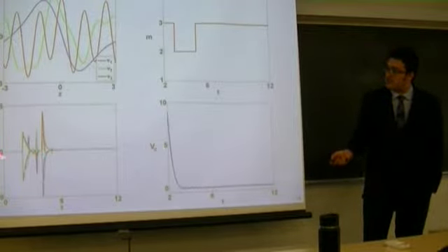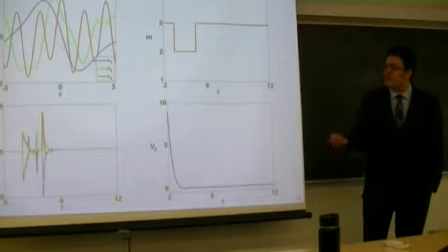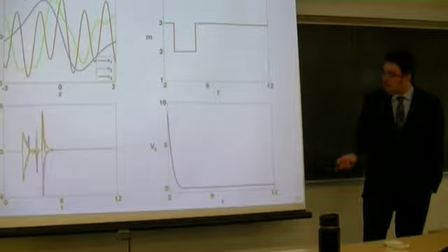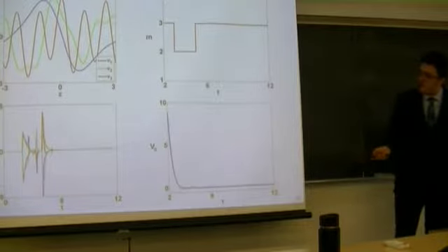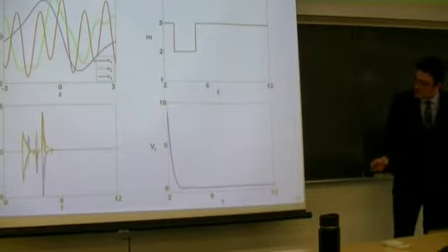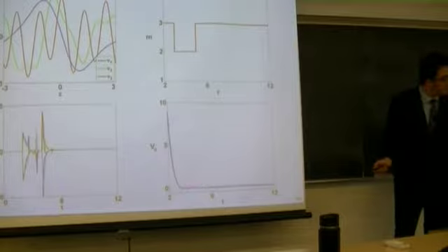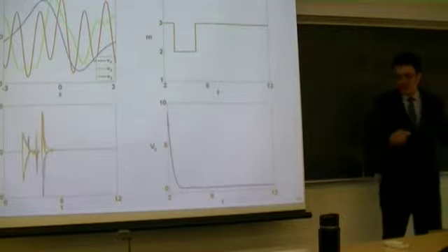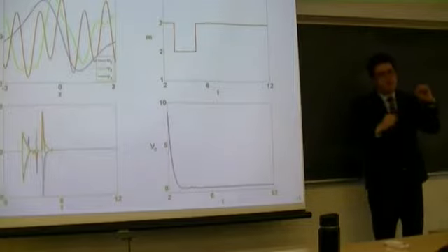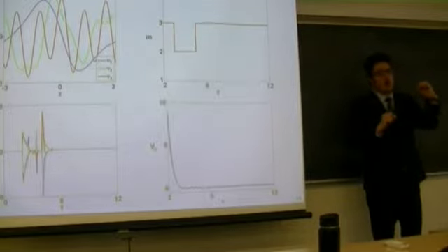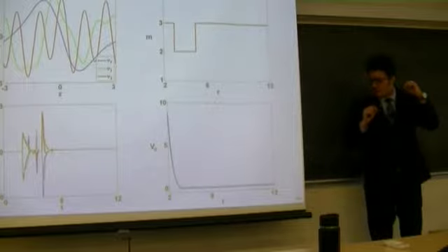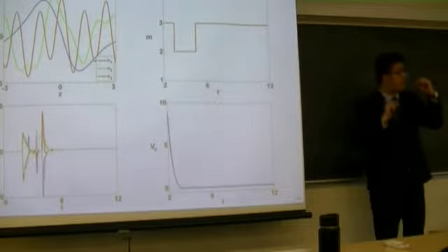Obviously, for the first 2 seconds of the process, the control is inactive to collect the required data. And this figure shows the monitored control Lyapunov function. As you can see, at some points we detect an increase. But since we are periodically revising the reduced order model, this will not affect the stability criteria.